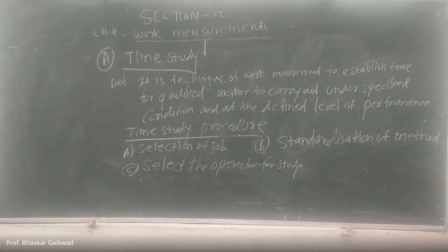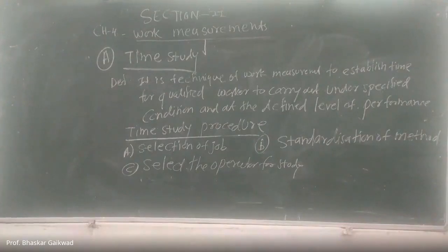It is better to ask foremen or repetitive workers to suggest the operator. The person selected should be skilled, and his speed of work should be average, close to the average. Use of a foreman for time measurement should be avoided. Whenever a skilled worker with good performance is there, we have to select such operators for the time study.